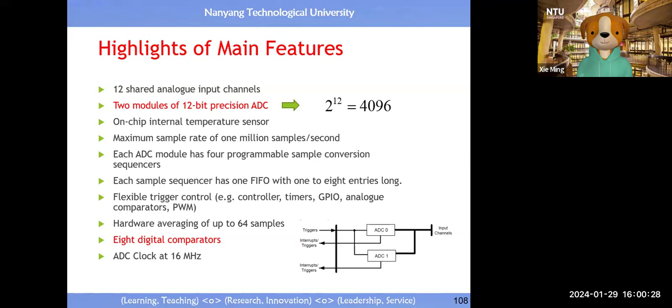You say, why not just give me one sampling device and one quantization device? Then my life is easier because I only take care of one sensor. But you see, with one node of ARM Cortex M4, now you can attach how many sensors? 12 analog sensors. Now you imagine you can construct a three-dimensional IoT network with asynchronous serial communication.